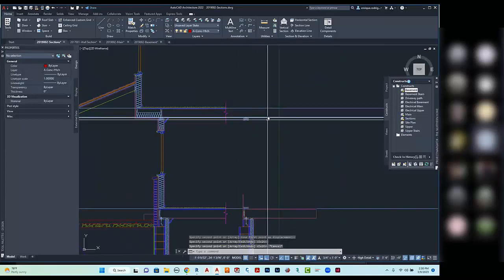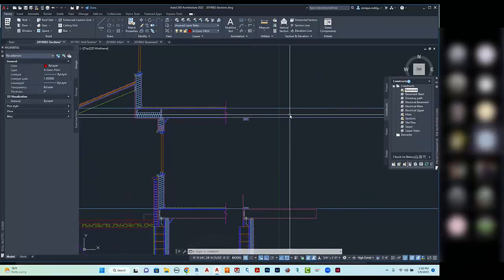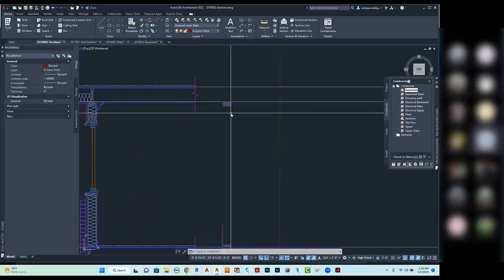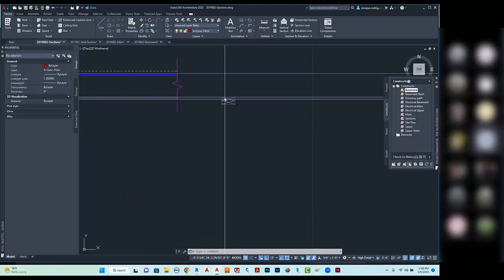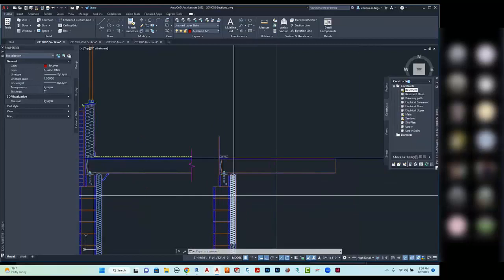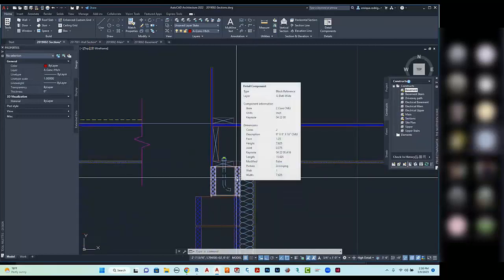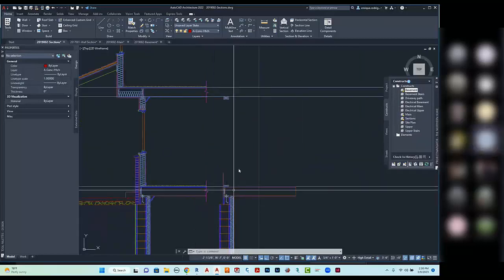Again, because it's holding the weight of all the floor joists that you're going to have in here. So this adds a little bit more strength than the singles. This is normal to the construction industry. The reason we didn't do it here or here is because it's supported along the entire length by the block underneath it.